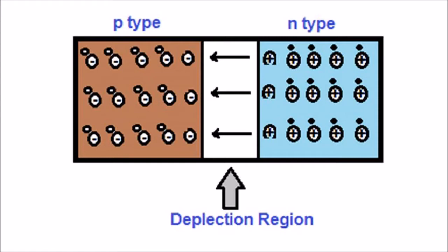If the junction was constructed of two separate pieces, this would introduce a discontinuity in the crystal lattice, so p-n junctions are created in a single crystal of semiconductor by introducing certain impurities called dopants, for example by ion implantation, diffusion or epitaxy, that is, growing a layer of crystal doped with n-type impurity on top of a layer of crystal doped with p-type impurity.